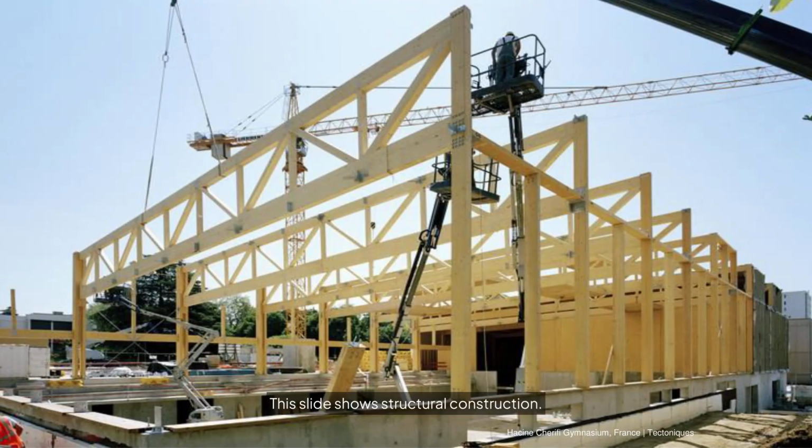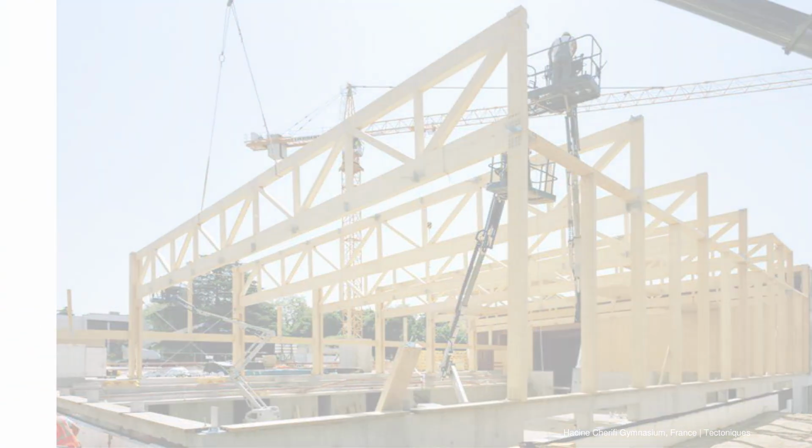This slide shows structural construction. The portal frames are made of glulam structures. They were manufactured in a controlled environment and then assembled on-site with bolted connections. Off-site prefabrication contributes to circular construction because it improves quality and precision with less material waste during construction. Prefabricated components can fit perfectly and potentially be taken apart with less damage.